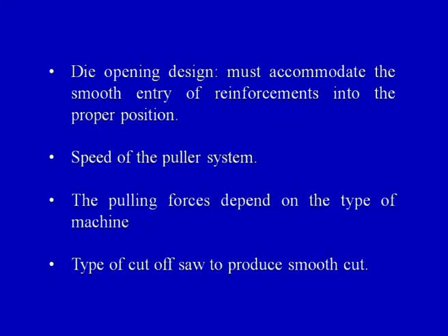So, it has to be taken into account that either a jacket of a wear resistant material is put inside the actual die, or the die is made of such a material which is wear resistant. Then the die opening design is also equally important, must accommodate the smooth entry of the reinforcements into the proper position. So, the die opening design is very important because the raw material in the form of resin impregnated fibers have to get in the die, and finally the final product has to come out of the die.